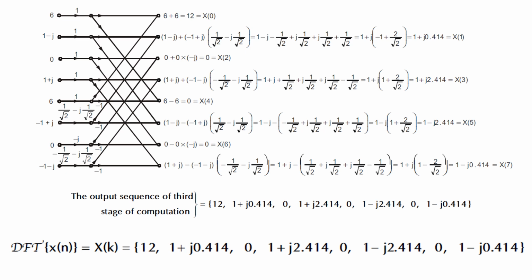Similarly, for the remaining 3 points, the value is calculated as per the algorithm as we have done with the above lines. So upon simplification, we'll be getting the output. So this is the output of the DIT FFT algorithm. So x of 0, here we can find upon feeding the input that is in bit reversal order, but the output is in natural order, which starts from 0 and ends at 7.